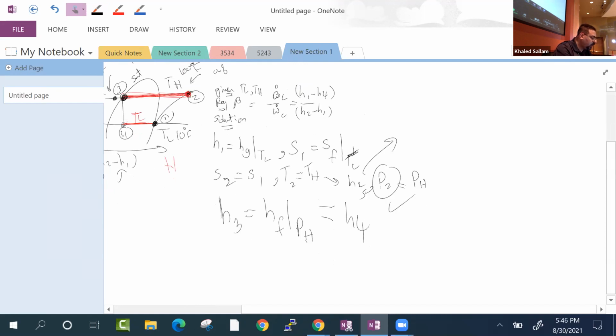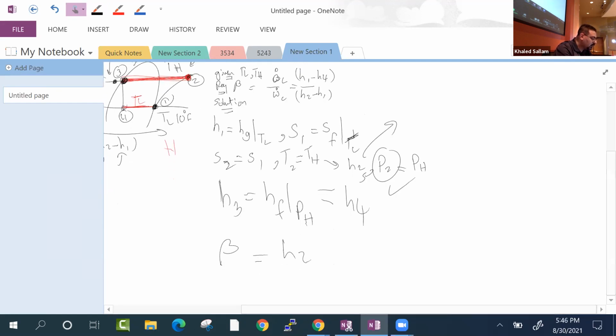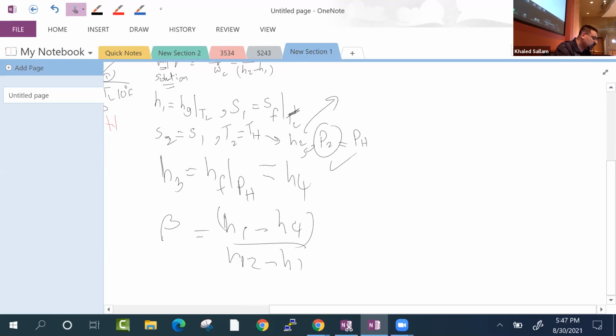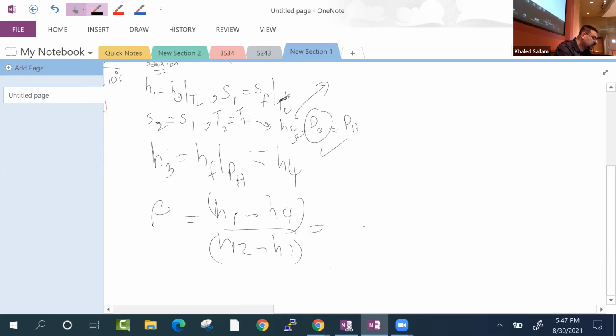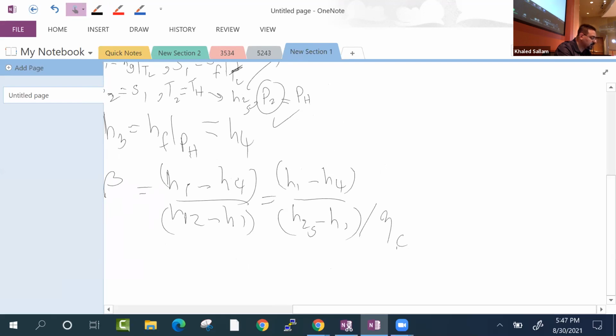It's just that when we do the eta and we would like to say H2, it's H1 minus H4 divided by H2 minus H1. So that's not H2s, it's H2. So what do you do? You would say, well, H2 is going to be a little bit bigger than H2s. By how much? By eta compressor, right?